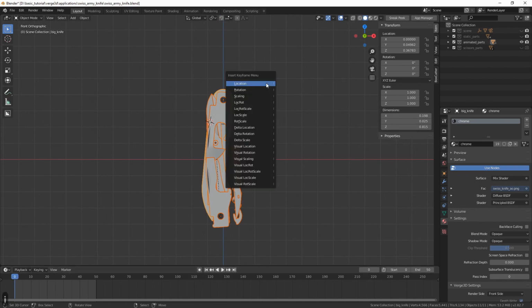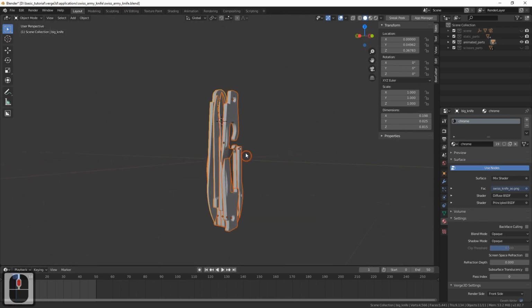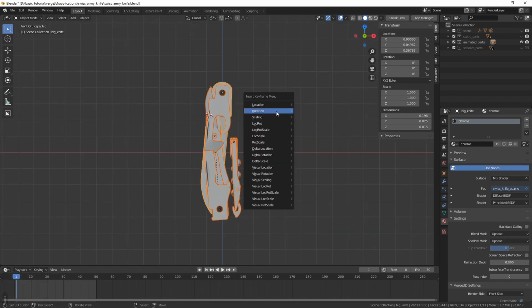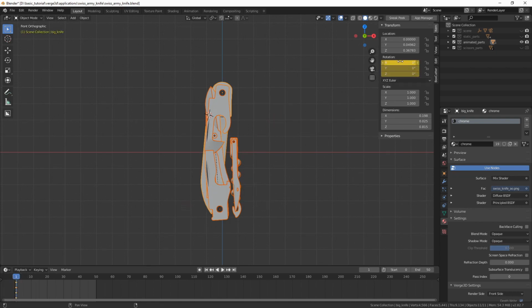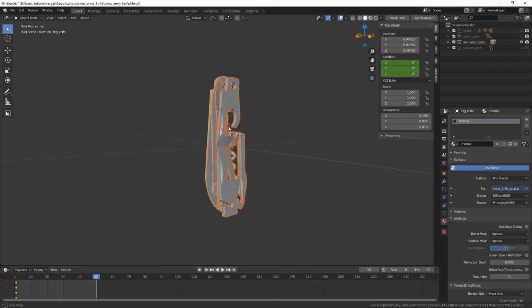First of all, let's freeze the starting positions of all instruments. Select all the instruments and set the current frame to 1. Use hotkey I on your keyboard to add rotation keyframes, which are added for all 3 coordinates. Now we can begin animating. Let's move to frame 50 on the timeline.